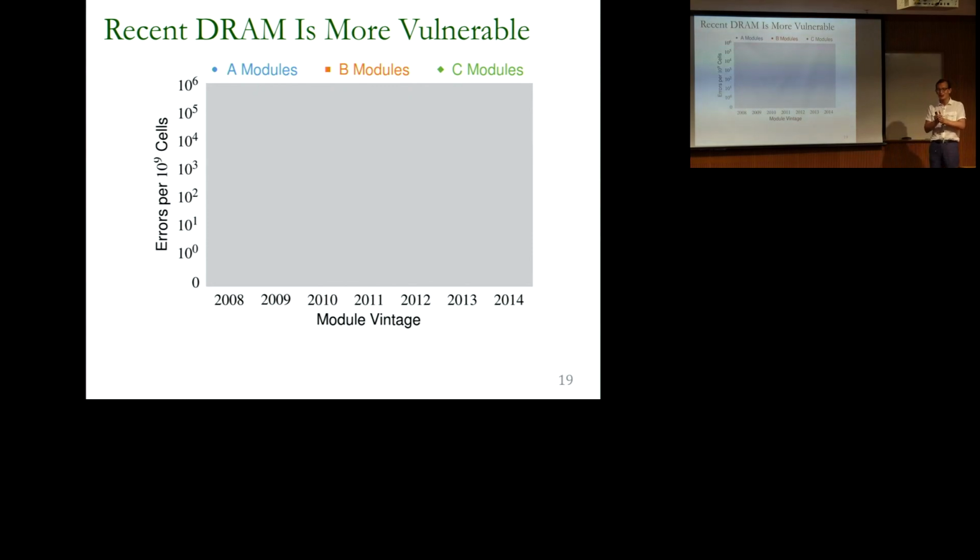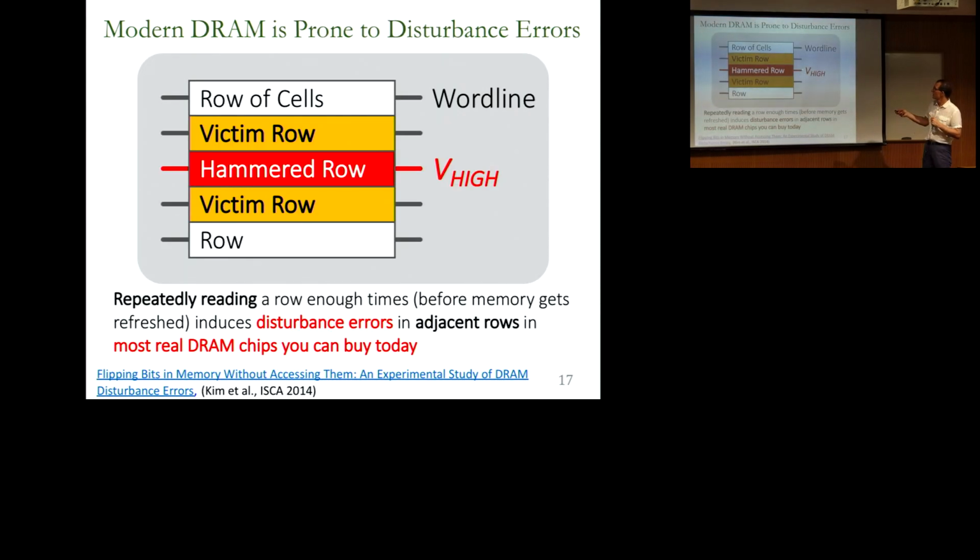They're disturbing each other. There's not enough electrical isolation. Whenever you activate this row, you're actually affecting what's inside the other row. And one mechanism that induces this is electromagnetic coupling. Whenever you're activating this row, you're slightly activating this other row over here, which means that you're opening up this row very little. And if you do this enough times, charge is leaking very little from the vulnerable cells over here. And if you do it enough times, you corrupt one or more of the vulnerable cells in the victim row because you've done too many of these hammerings.